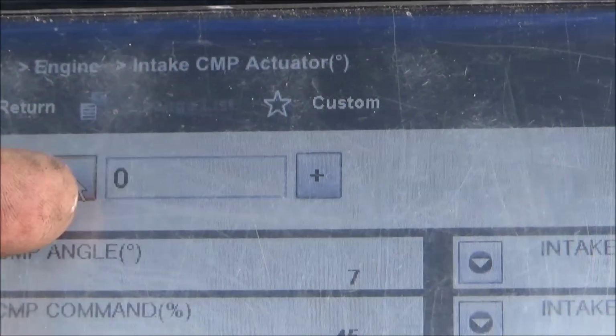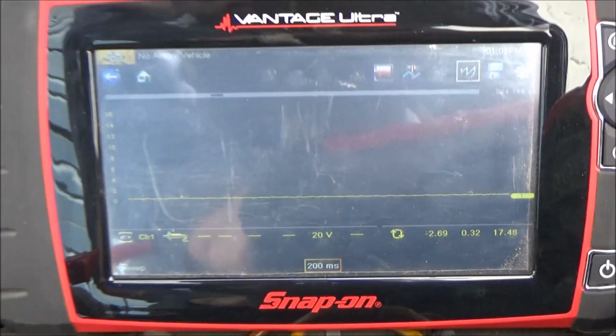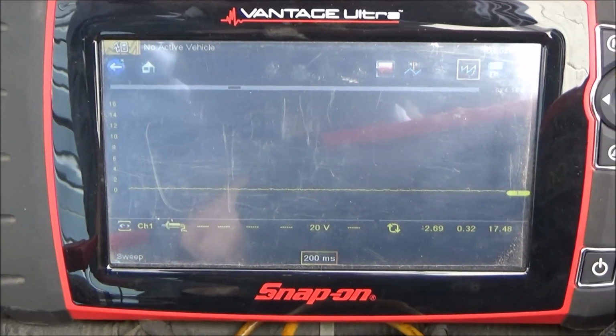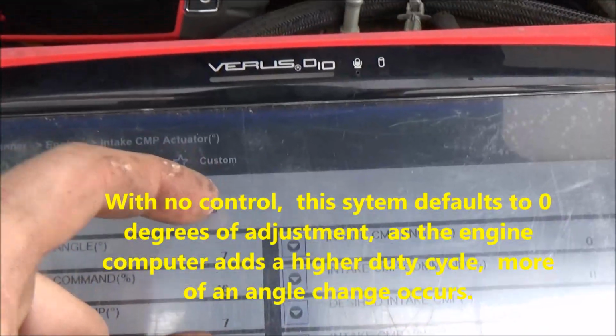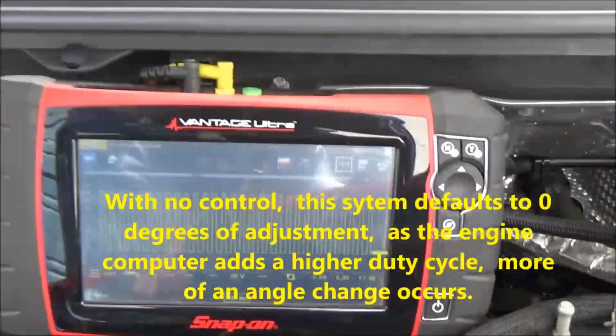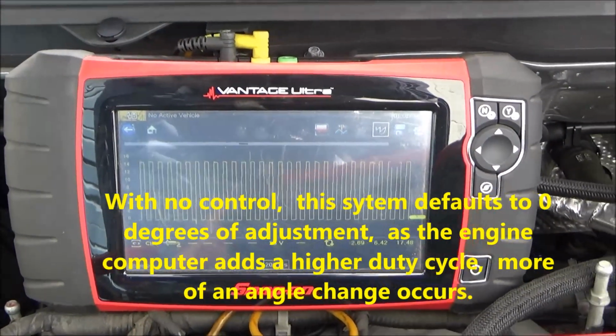And what I'm going to do first is turn this solenoid completely off. As we can see, taking a look at our Vantage here, we currently do not have any power side control to this solenoid. What I'm now going to do is ramp this up. This 10-degree number should be fine. And if we look back on the Vantage, we can confirm that we do have power side control there.